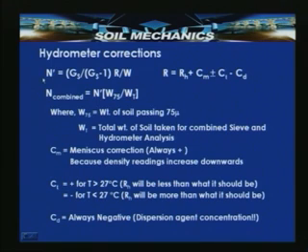That means N dash is equal to GS by GS minus 1 into R by W, where R is equal to RH plus Cm plus or minus Ct minus Cd. Once we get this, N combined can be obtained as N dash into W75 by Wt. W75 is the weight of the soil fraction passing 75 micron, and Wt is the total weight of the soil taken for combined sieve analysis as well as hydrometer analysis.